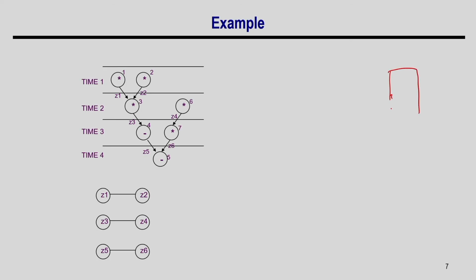So, the idea is like this. We have a set of register banks. This is my register bank 1, say it has 5-6 registers. There is another bank which has say 4 registers, and I am not going to access these registers individually. Rather, I will have a port here, a read-write combination port.